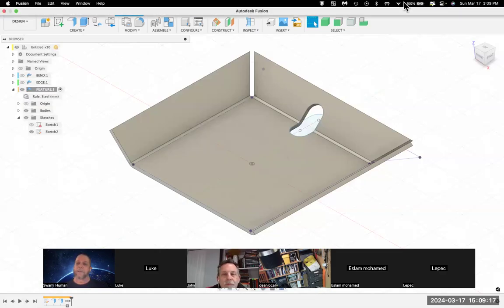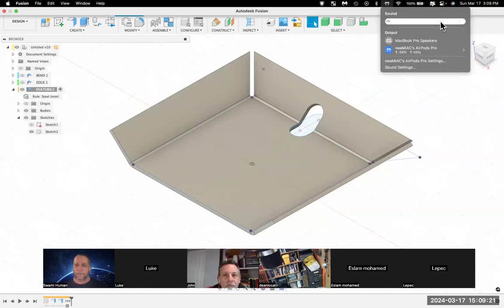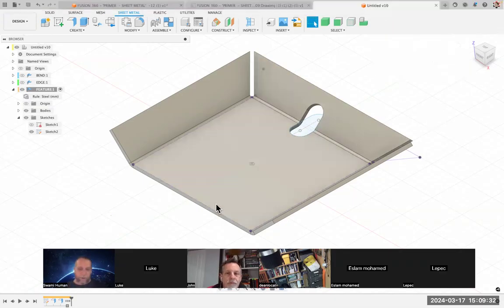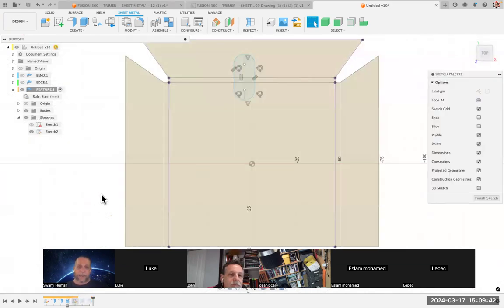Right before you drew the slot, you selected a sketch, like a surface. Could you repeat that little process so I could see how you selected that plane to get all the lines to show up? Yep. So that was a project, and we will go ahead and do that for you. There are multiple ways to project, so I'm going to edit that sketch. So I'm going to find it wherever, double click it there.